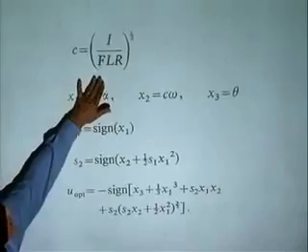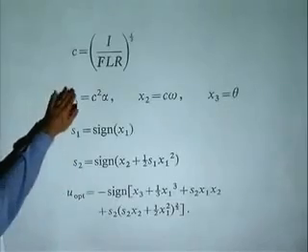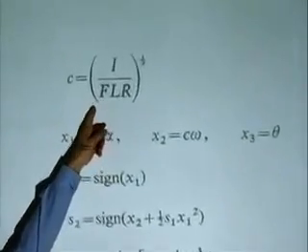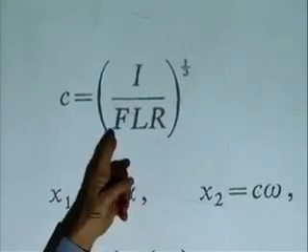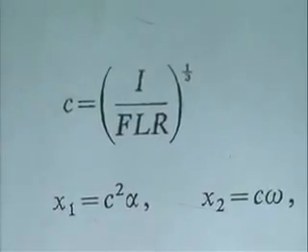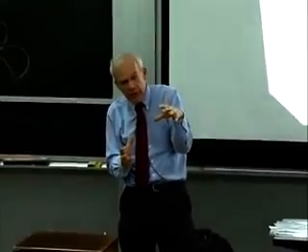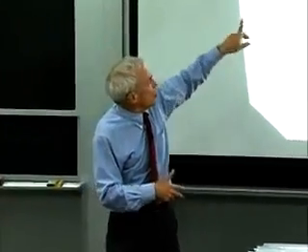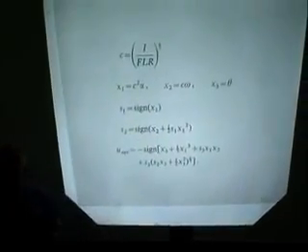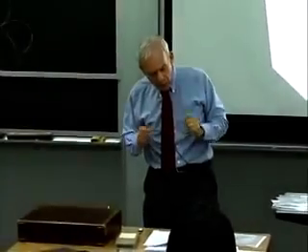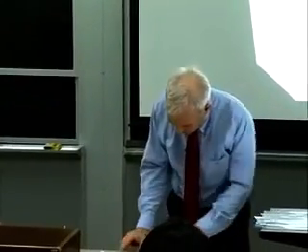I non-dimensionalized it because we didn't have floating point arithmetic. We're dealing with fixed point arithmetic. And this is the control effectiveness, the thrust of the throttleable engine, the distance to the center of mass, the rate at which the gimbal could be driven, and the moment of inertia of the spacecraft, whether it was this full enormous configuration or whether it was just the LEM itself almost out of fuel descending to the surface. So, I mean, there are huge ranges in this control effectiveness. So we non-dimensionalized the equations so that they could be programmed within double precision fixed point arithmetic. And it went really well.